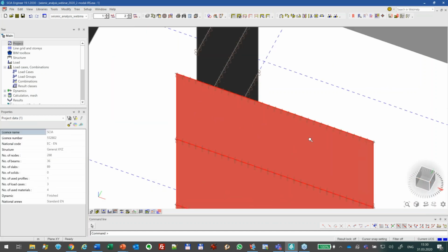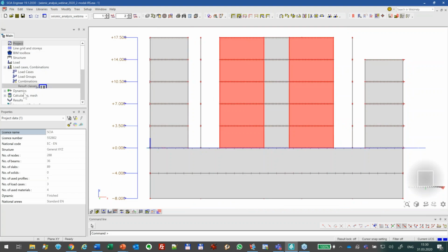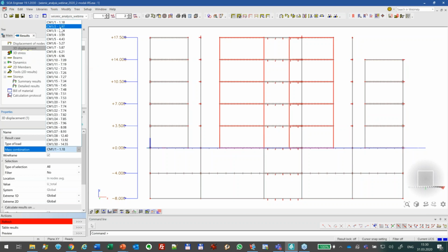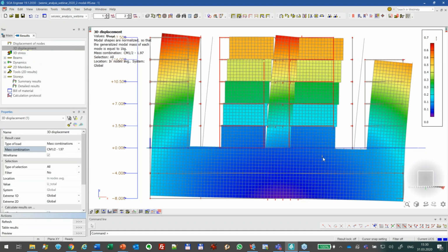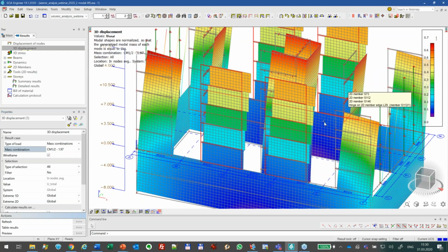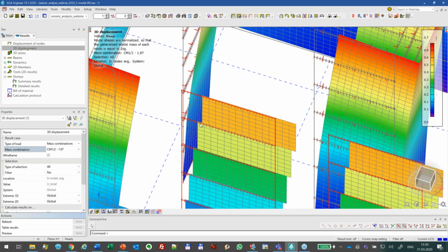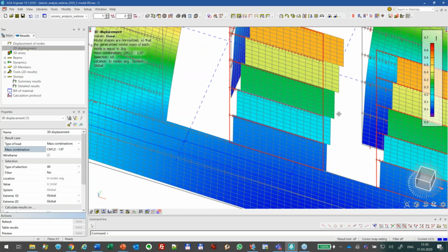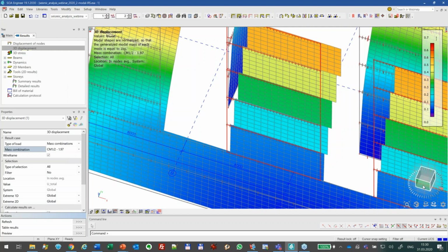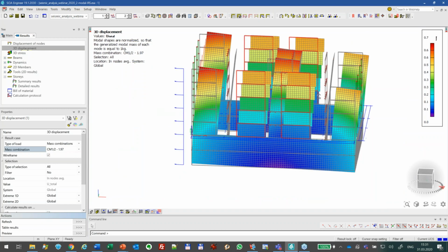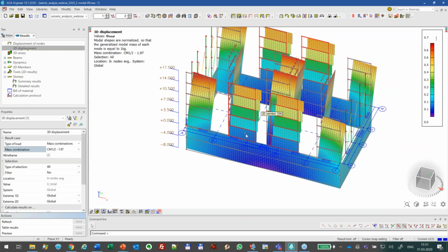Maybe you noticed when I showed the mode shapes, I can show it again. Let me show here, and most interesting is mode number 2, which is in direction X. You can see clearly here that my special hinges are acting there and that my masonry walls are nicely disconnected. They just slide on the top of each other. They don't get that typical bending deformation that my concrete shear walls have here. Here we really have a nice bend shape. And the masonry walls, on the other hand, just remain undeformed, but they just slide on the top.